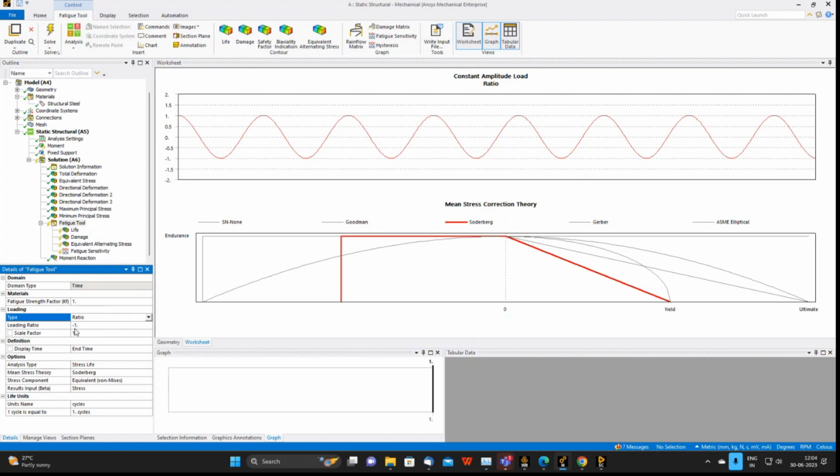Here it has been taken as -1 and 1. We can change the values here so that whatever the stress 141.85 will be included for the tensile, and half of it will be included for the compressive load. That is the factor we are going to use here. Let's keep it as -1, that is equal.